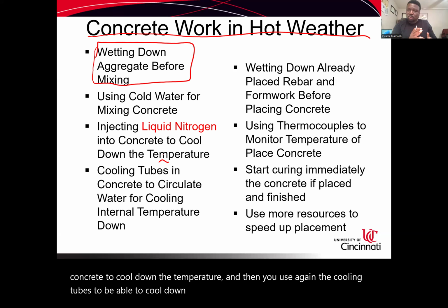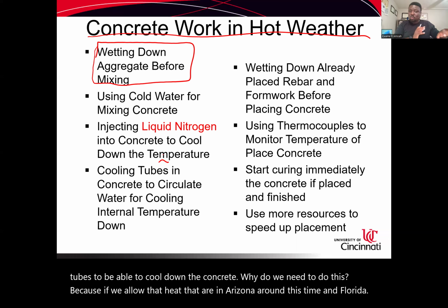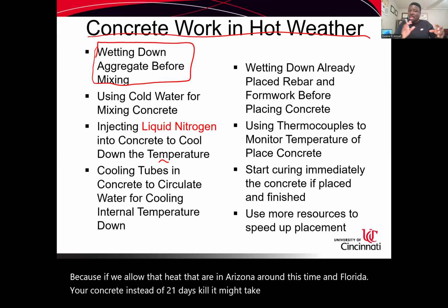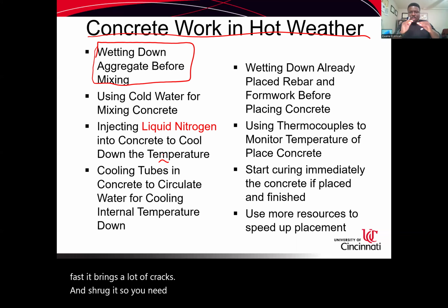Why do we need to do this? Because if we allow that heat that is in Arizona around this time and Florida, your concrete, instead of a 21 days cure, it might take like 3 days. And because it dries fast, it brings a lot of cracks and shrinkage. So you need to cool it down to settle or cure normally for you, right?